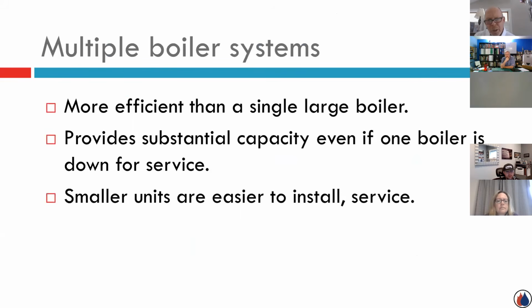A couple of other benefits: more efficient than a large boiler, and substantial capacity even if one boiler does go down for service. And from a physical standpoint, for installation or renovation of an existing plant, smaller units might be easier to install and easier to work on down the road.